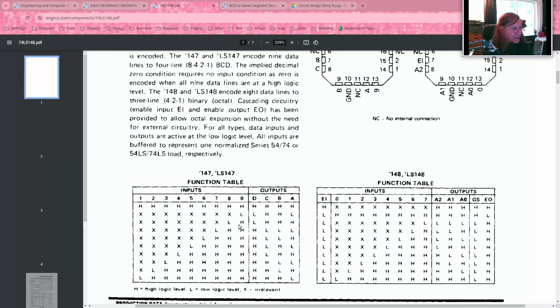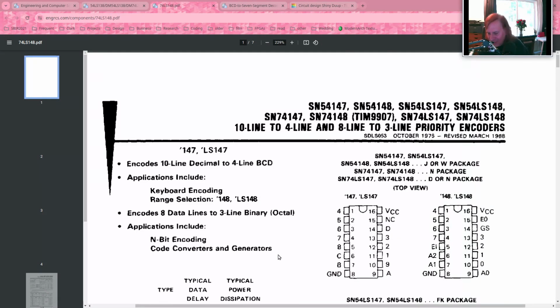could use a circuit like this and say, hey, what's the most important thing that's happening right now? Someone got my attention. What's the most important thing I should deal with? And if it sees this, it knows, oh, the power's failing. Okay, I need to save the contents of memory somewhere where it won't be lost, and then I need to do an orderly shutdown. Or if the input generates this, it says, oh, somebody pressed a key. Okay, I can go deal with that because there's nothing more important happening right now. So this is something we'd find inside a computing system.